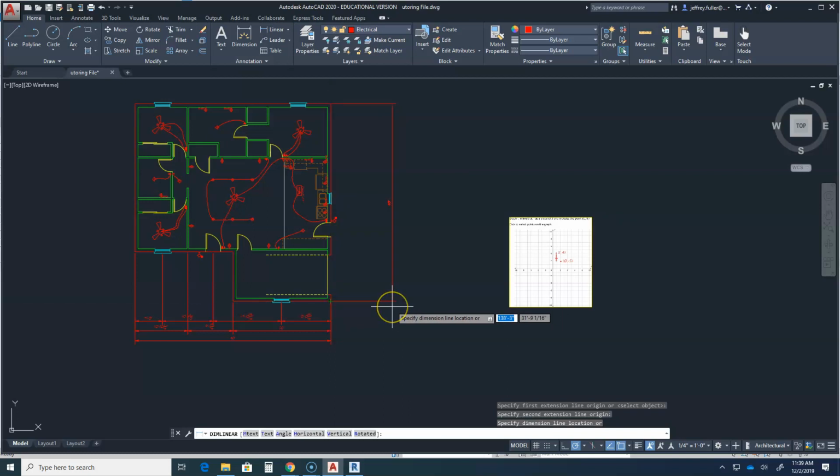Okay, stretch it out, and this one is going to be at 8 feet. That is the overall. And because I'm moving in the Y direction, no, I'm sorry. Let me take that back. I'm moving in the X axis direction, and I want to put that at 8 feet. So I'm going to put 8, and it's in the positive direction. If I was moving to the left, it would be a negative. So I'm going to do 8 feet, tab over to the Y, and make that 0, and enter.